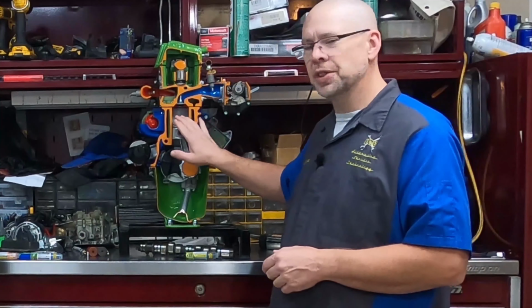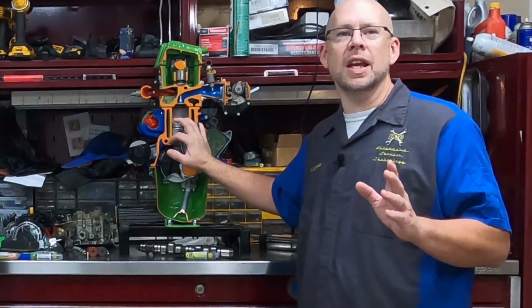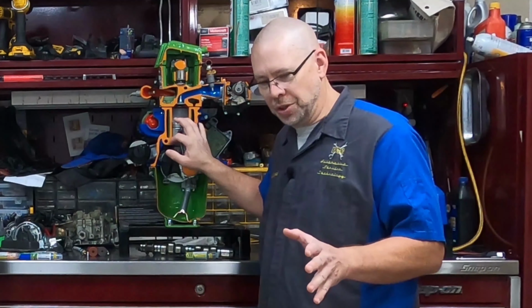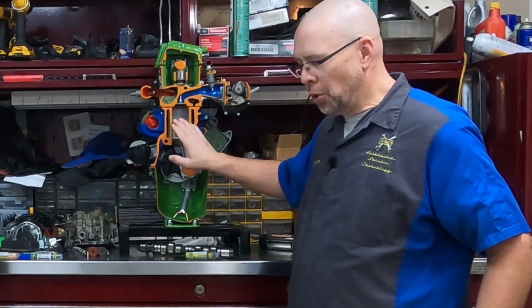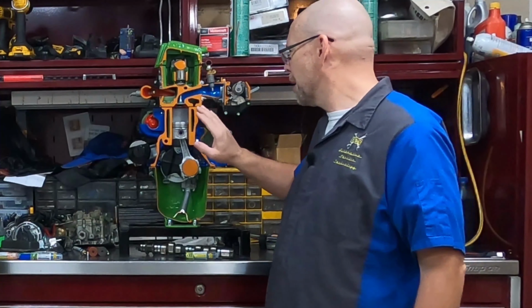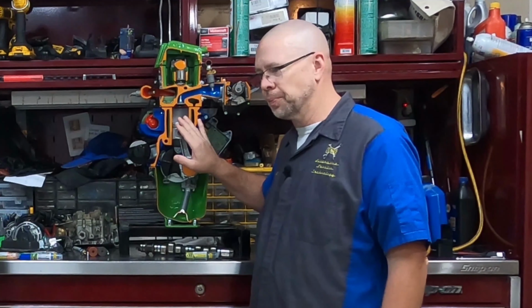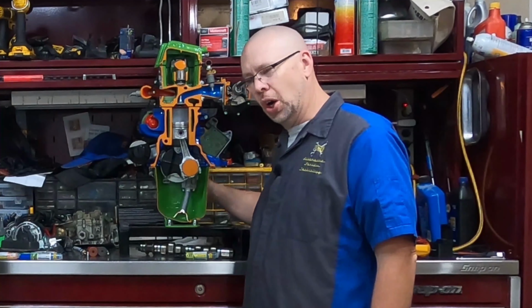The load driving down the freeway. If we're driving down I-5 at 2,500 RPM in fourth gear on a flat stretch of I-5, that is a completely different load than driving up Mount Hood in fourth gear at 2,500 RPM. It's a different load. We're asking the engine to do a different amount of work. Now that comes into play because when we increase load, we increase cylinder pressure. In fact, it turns out that any time we increase cylinder pressure, whether it's through load, whether we add boost, no matter what we do, if we increase cylinder pressure, we actually have to back the timing off a little bit.